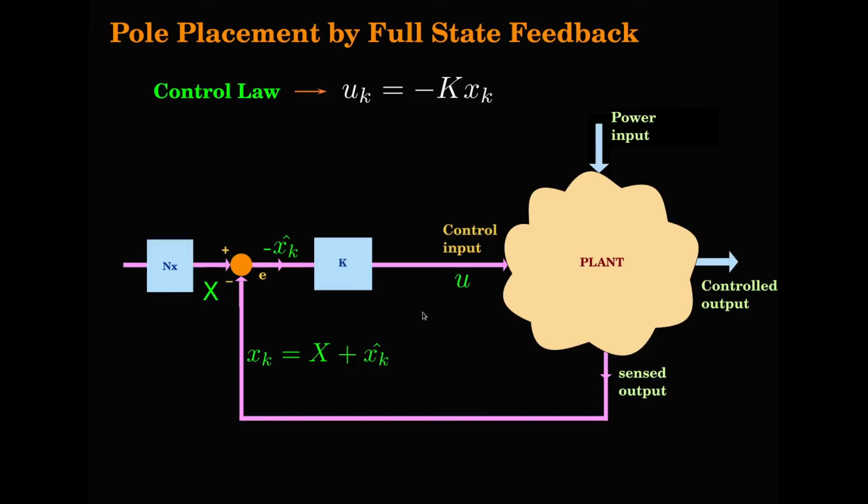But we also have a feed forward aspect which will come in. So let us say this is Nx, another fixed matrix, and what is its job? From a known set of reference values. For example, if I am doing speed control of a motor, so what is fed back? If I take a DC motor, we have seen that there are two states. One is the angular speed, and the other one is the armature current IA. So let us say we are feeding back IA and the angular speed.